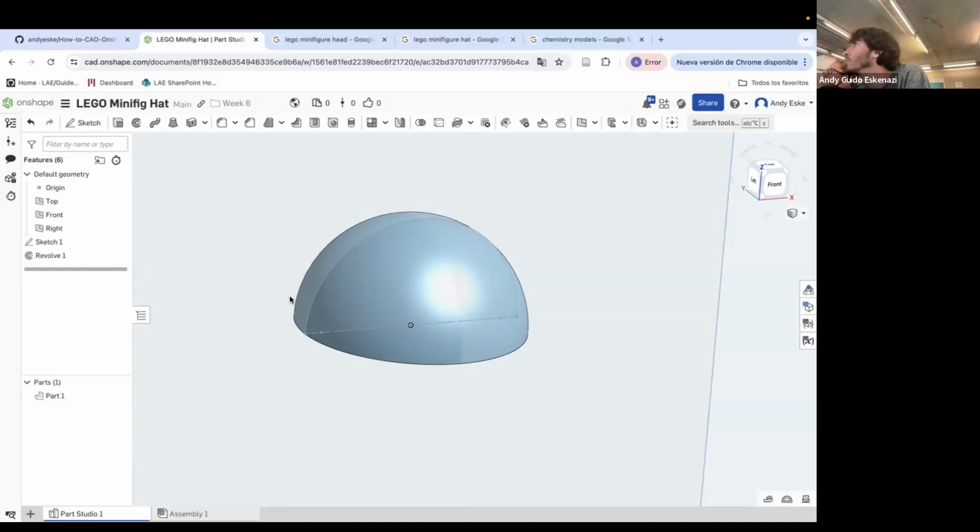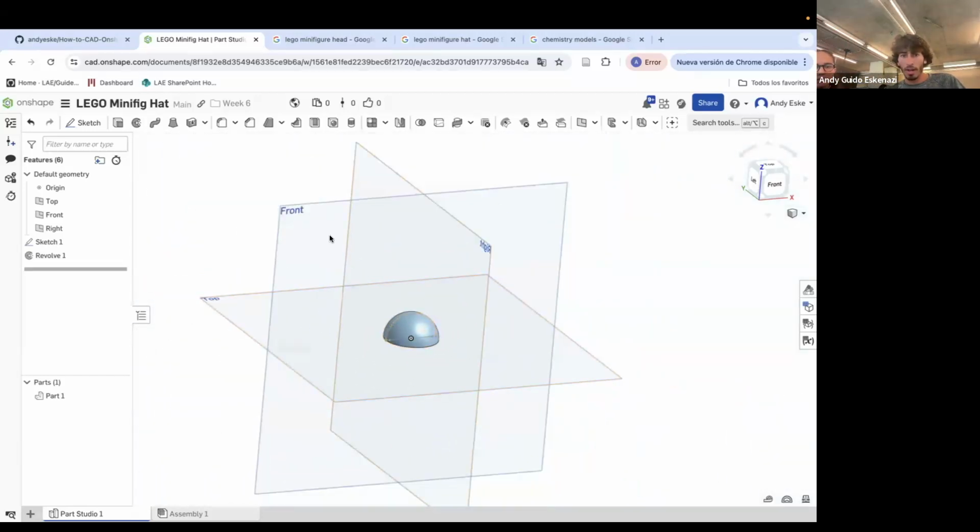And now what we can do is just a solid line that goes like that, and a 3 point arc that goes like this, and then revolve. That will do 2 directions, 90 and 270. Perfect. Okay, and then show the sketch. Good. So now that we are at this point, and it is exactly where we are, I'm gonna do another sketch.